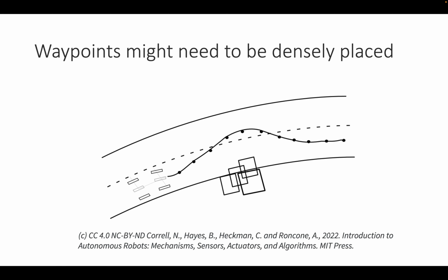In practice, waypoints are really what robots would use. So an autonomous car might use a topological map to travel from one node to the other, which are the intersections of the road. But once you are on the road, you want to put waypoints in front of the car to determine the trajectory that the car should take.